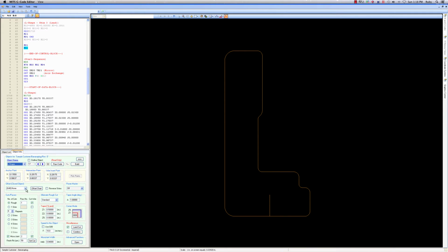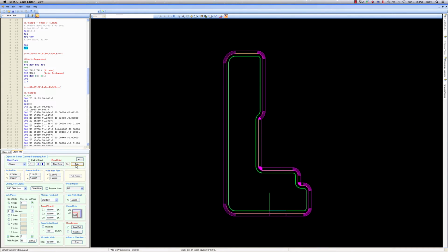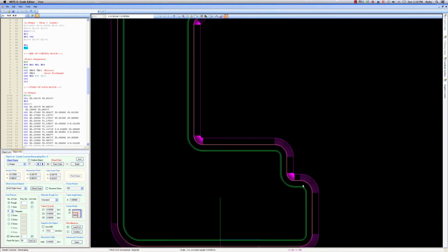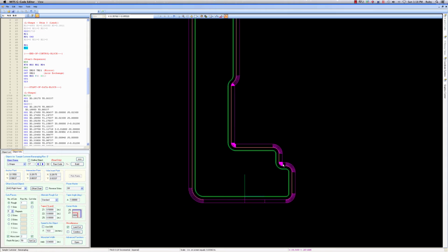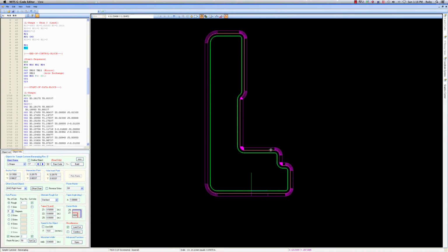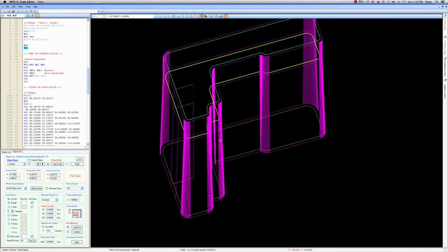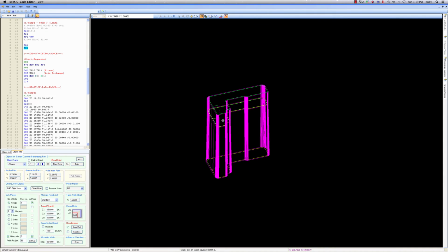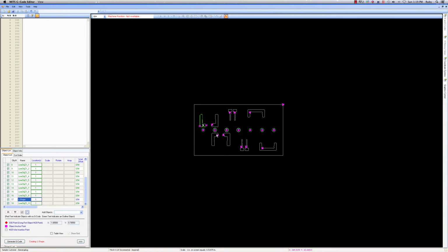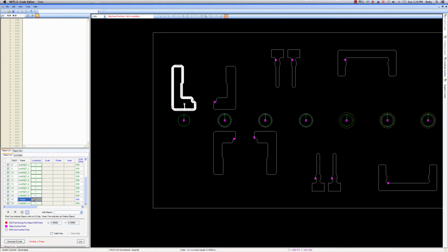Missing our offset. Give it a right hand offset and we will try again. There it is. When we set a taper, we must make sure that we do not cause problems at the bottom in case it's too large. We can view this one. We'll go back to our object list and we will add the next 3 into it.